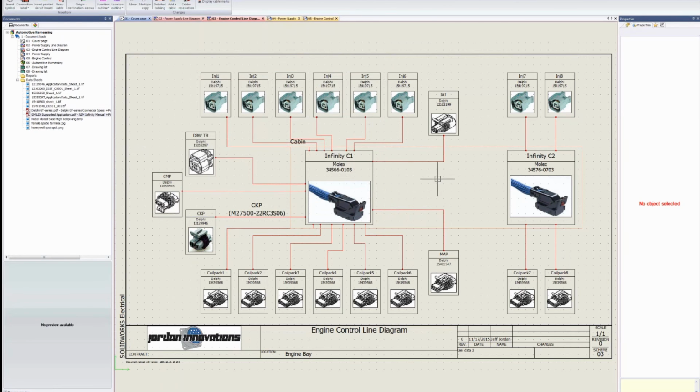Now the other way to do this, if we want to do everything with discrete cables, is something like my crank angle sensor. This is a Hall effect sensor, not super high speed in terms of industrial or gas turbine engines or anything like that, but automotive is a pretty nasty environment. So I'm going to use a 22 gauge shielded cable for this.